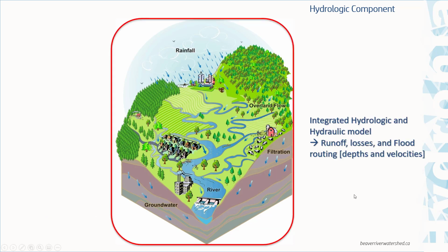Well, in the case of the hydrologic component of the HydroBID flood, the philosophy is to integrate both methodologies, because both methodologies are interconnected. From the physical point of view, both the hydrology and the hydraulics are occurring at the same time. In the sense that, first of all, the rainfall not only occurs in the upper basin, it can also occur over the urban area that we're analyzing, where we're analyzing the flooding problem. Therefore, in this case, we can consider that rainfall over the whole basin. And in addition to that, analyzing the different components of the hydrologic cycle, we are going to define that runoff, the surface runoff component.